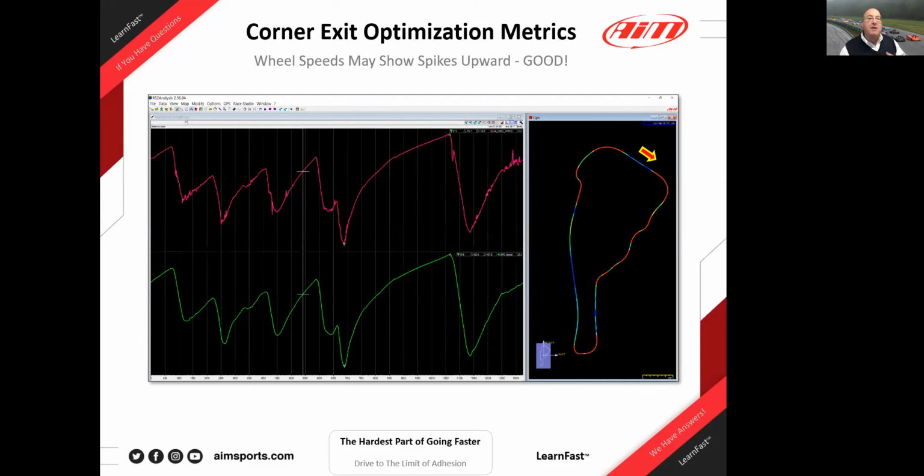One of the things that most drivers, and I would say a majority of the club drivers that I work with, don't do is they don't drive the car to the point where it pushes back. They turn the wheel and the car turns. They maintain the steering angle and the car tracks a radius through the corner the way they want it to do.